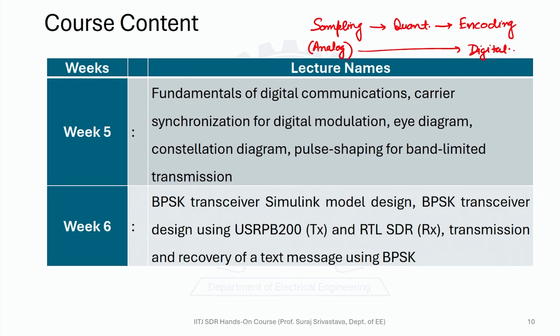So the digital modulation schemes basically require the message source to be digital in nature. The message source can be digital in its original form, or it may have been obtained using sampling, quantization and encoding into digital form. In both of these cases you can use digital modulation techniques.